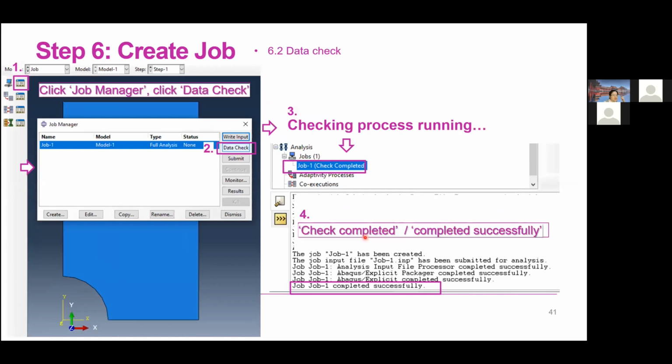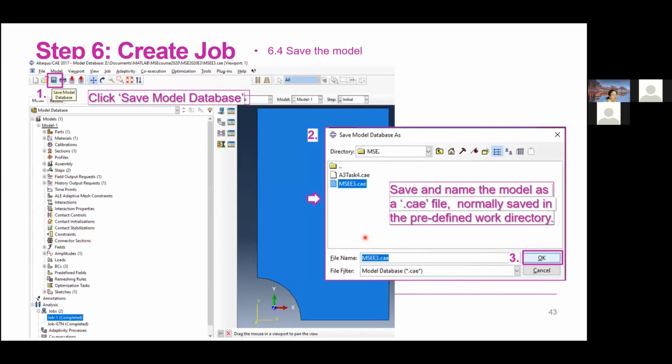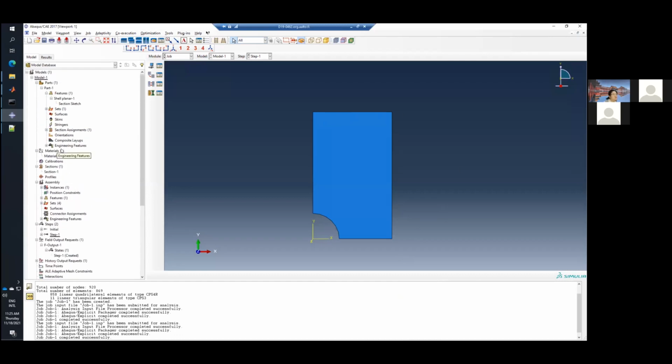FEM simulation actually. So if you did not follow it, you will see all the details here. And afterwards, you can save your CAE model. This model is called the CAE model with all the detailed options inside. Then you can directly save it, and next time you can open it if you want to modify the geometry or modify your boundary condition slightly and so on. You can do the modification inside instead of generating a new model.